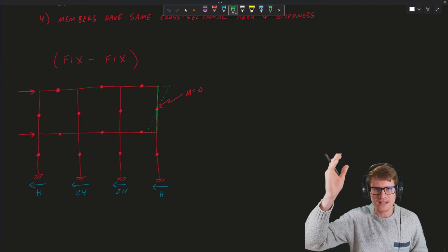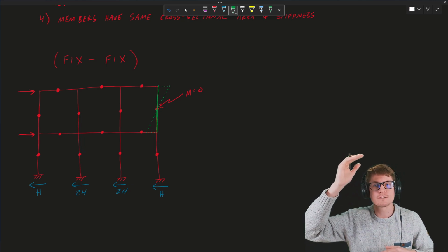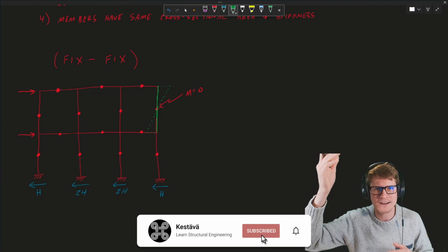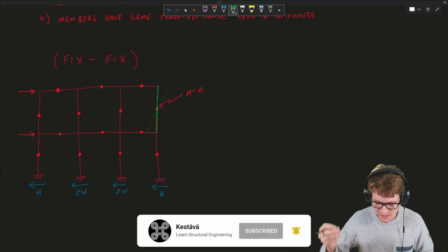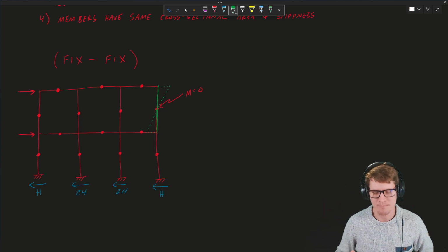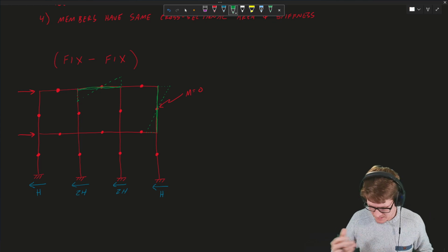It's equally stiff at the top as it is at the bottom, so the load distribution is going to move to the 2 stiffest portions of the column in this matter, and so your moments accumulate at both extreme ends, meeting in the middle where it will be 0. This is the same for all of our beams as well. And so on and so on and so on.